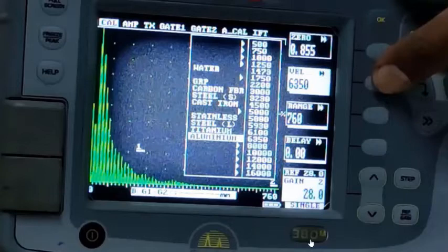And we are also going to use some samples or standard blocks having standard known depth or distance to show how the display of the signal will come from a particular distance. So let us first see how this instrument can be calibrated, and how exactly it is done using the different buttons that you have. That process may vary from instrument to instrument, from make to make, right? But the objective is to calibrate the instrument and the ultrasonic transducer at the end of the process. So let us go ahead and see that first.